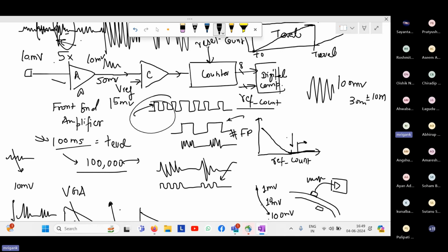So in that case, even a crystal oscillator can be used to generate the on-board clock, and that clock can be used by this chip. PLLs are used when we want to synthesize a higher frequency clock. In this system, we don't need a high frequency clock, so there is no need of a PLL as such. Also, PLLs are used when you need a very well controlled or controllable frequency. Here, there is no such stringent requirement. So yes, an LDO will be required for the first two stages. The second two stages can work with a nominal frequency clock obtained from a crystal oscillator.